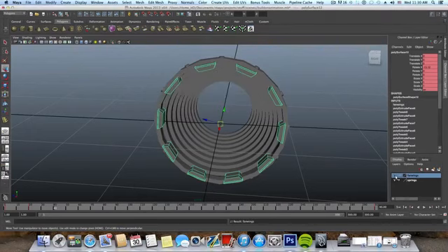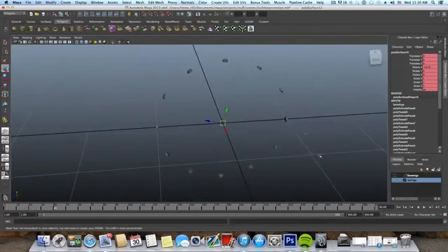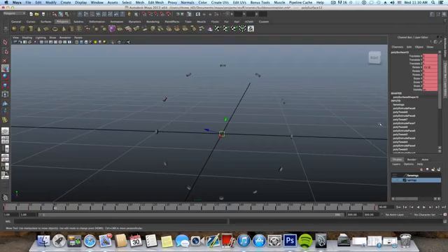So we have those cylinders right now, and I want them to appear at frame number 40. I will immediately press S to keyframe at frame number 40, and then I will go one frame back to 39, and switch the visibility to 0, which means off, hit Enter, and press S. Now I want to explain why I'm using the big Enter key and not the side one near the numbers.